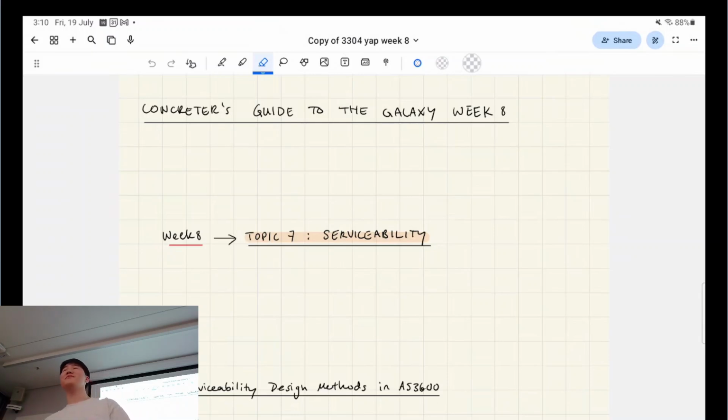So typically when we think of deflections, we think about slabs because they deflect more. It's one of the limiting factors rather than beams. For example, the roof of this room, that's a slab. It's basically like a 2D version of a beam, right? And you can imagine the max amount of sagging might occur in the middle. So if you looked up at the ceiling right now and it's sagging down, you'd be like, okay, well, something's wrong with this room, right? So that's what we had designed for essentially, right?